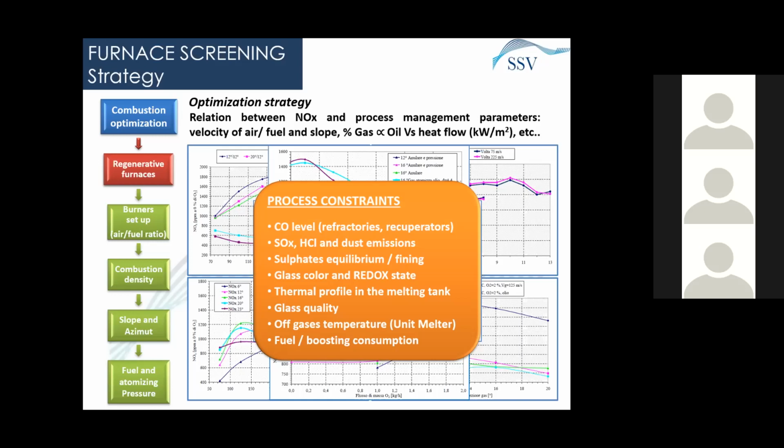At the same time, it's important to take into account the thermal profile in the melting tank, which is highly correlated with glass quality. And also there are the fuel boosting consumption and the temperature of the waste gas going out from the furnace.